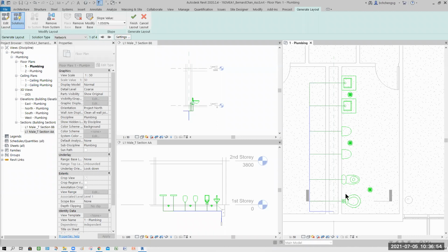So that's why this is nearer here, right? You flush, you go down this way. It won't go up because of the sloping. And also the fitting direction is important. Fitting direction will depend on the slope percent. So if you do this slope percent wrongly, good luck to you. It's as good as you redo.